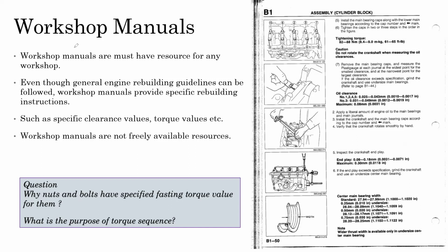So workshop manuals are important. Yes, where was I? Let's say for example 0.35, the valve is actually made of titanium alloy. The titanium is not expanding as much as in the normal chromoly alloy valve. So you don't have to keep to 0.35, which means if you keep 0.35, the valve opens a little bit later, right? That ends up reducing the engine's performance, and in addition to that, it will create a lot of noise.